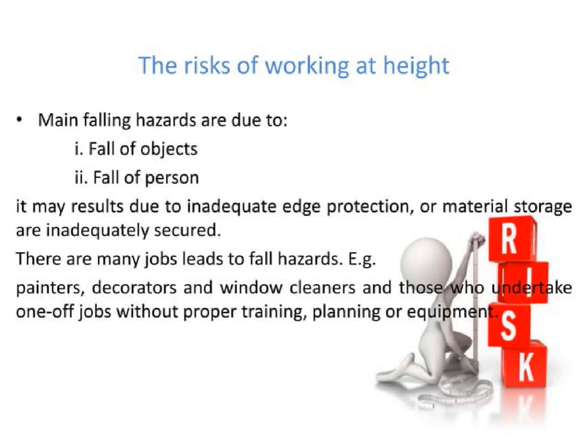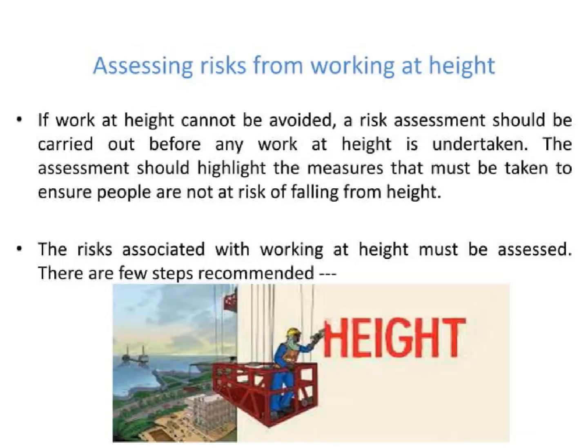While the main falling hazards are usually due to either the fall of a person or the fall of an object, there are numerous factors that can contribute to this. Poor edge protection or improperly secured material storage can contribute to these hazards. There are many jobs that leave workers vulnerable to these fall hazards, such as painters, decorators, window cleaners, and those performing one-off jobs without proper training, planning or equipment. It is essential that all workers are aware of the risks and receive the proper training and protection to help avoid dangerous situations. It is essential to assess the risks associated with working at height before any work is undertaken.